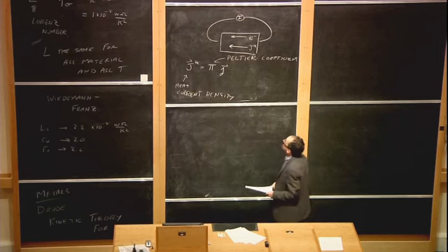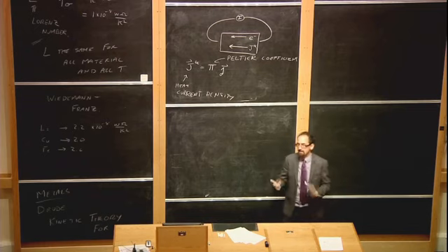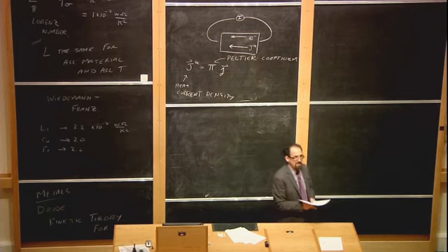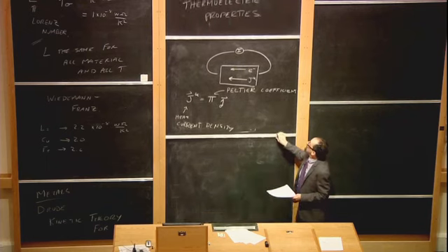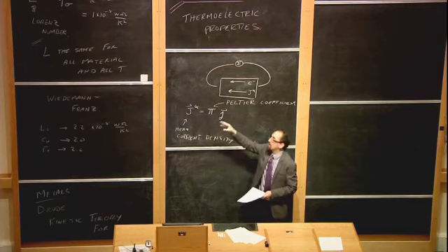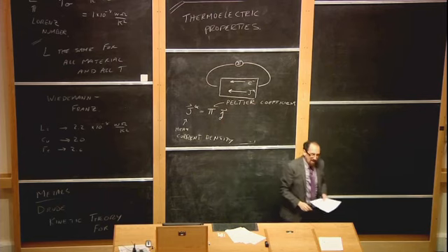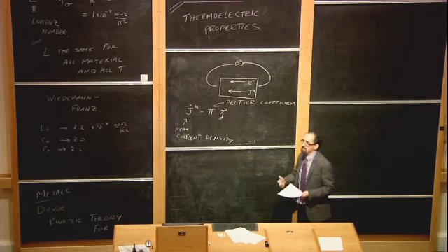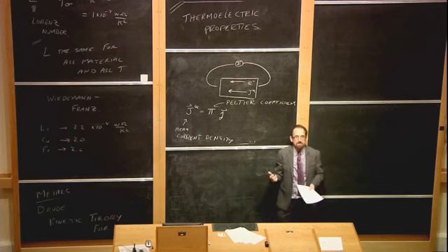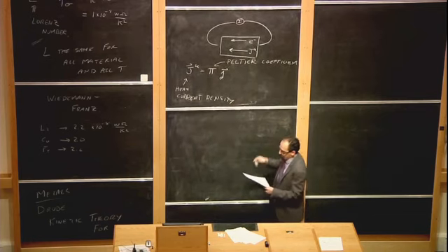Anyway, I should comment here as a bit of an aside that the Peltier effect is actually a very technologically useful effect to know about. You can actually build a very nice refrigerator with it, which has no moving parts. The idea is that if you want to move heat from the inside of your refrigerator to the outside, you just run current, and it drags heat with it, leaving this side cold, making that side hot. In fact, you can buy refrigerators that are built like this. They don't have pumps and things like that. They're not loud. They're very quiet. Frequently, they're actually used as wine refrigerators. I don't know why, but you can buy a Peltier refrigerator on the open market these days.